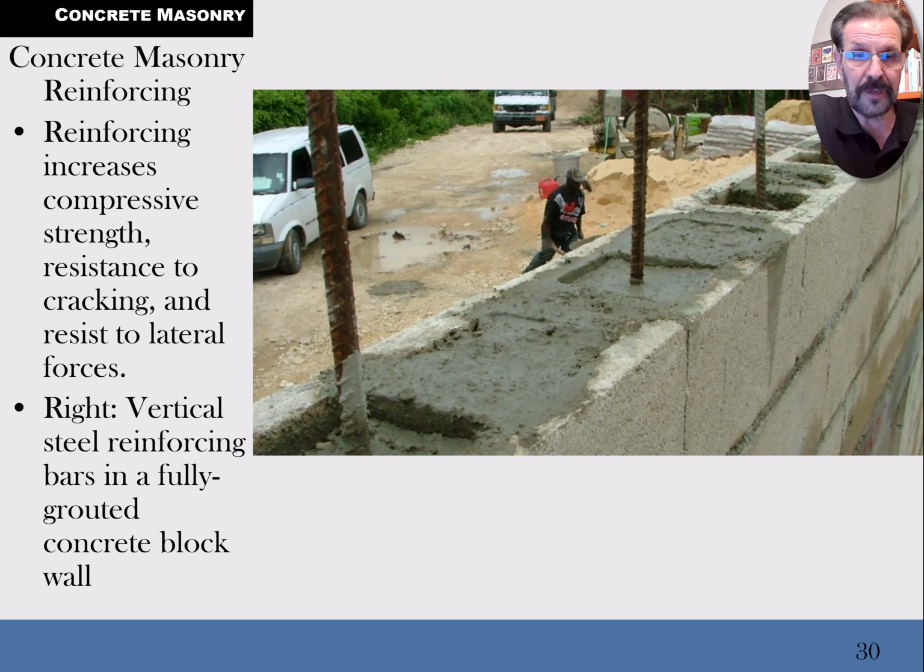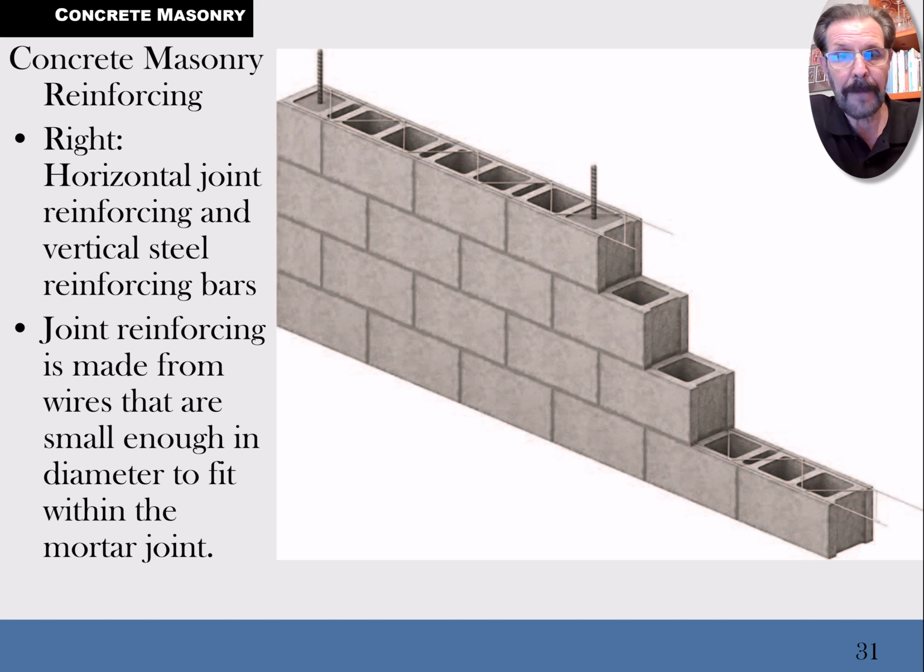And it's not just columns. We also have hidden beams. So come and take a look. Well, first of all, I got this picture, I forgot. This is showing mesh that's laid into the mortar along with those columns. The mesh by itself is not equivalent to having a proper beam hidden in that wall. It's nothing wrong with doing it, but it's not good enough by itself. That's not adequate.